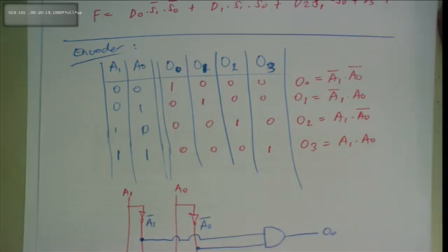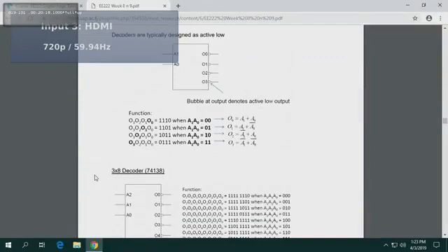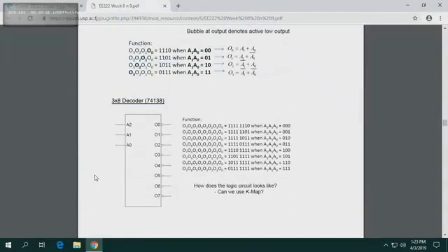If you've got a 3 to 8 decoder, let me just flip back to the computer. If you've got a 3 to 8 decoder and that's the only thing available, and they say, no, but we just want to use 2 lines from there. So what are you going to do? You take the most significant line and you tie it to 0. You tie it to ground, right? You connect it to a 0. 0 is a ground. And you only use the least significant bits, and that will transform itself to a 2 to 4 decoder in this case, all right?